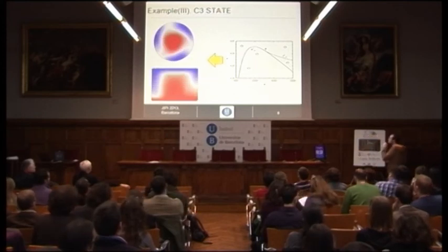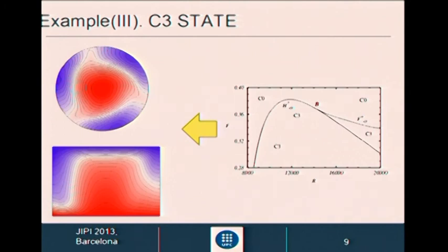This new solution is illustrated in these two pictures. Now you see how the axisymmetric character of the previous solution is broken, and there are three branches of warm fluid appearing. So this is what we call an intermediate state between the laminar flow and the completely turbulent flow, which will come for larger values of the control parameters. So this is basically what we do.